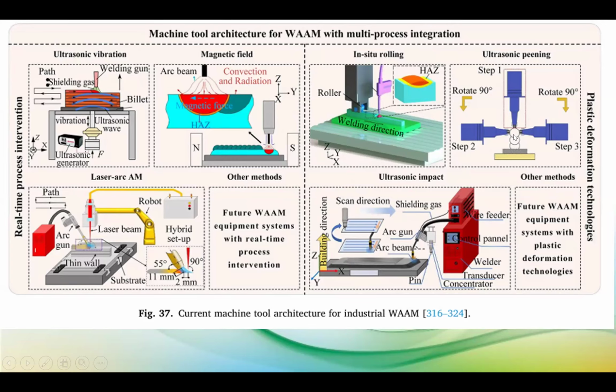The second method they are suggesting is a standard wire type filler material in which more than one type of material will be wound as a wire. Different materials, more than one, two, three, four, depending upon the combination and the requirement, you can have a wire type filler material. Here, depending upon the size of each strand, we can almost control the composition of the substrate.